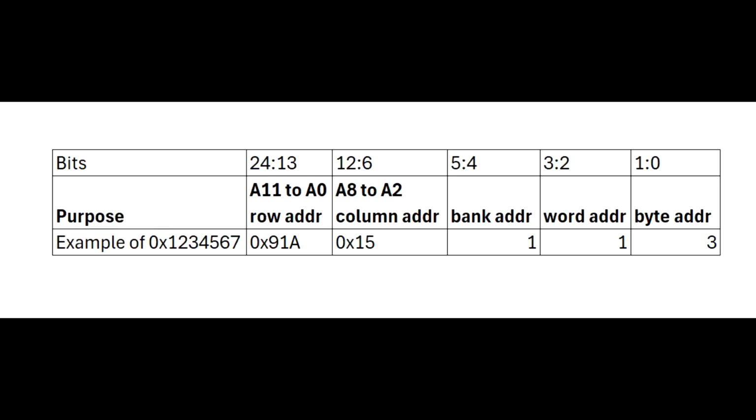Detection of 256 megabit memory is quite simple. We know that it can use the A8 bit as a column bit, and this is not possible on stock memory. So simply we need to be able to set that A8 column bit and see if the memory responds like a 256 megabit memory. By doing some reverse engineering, I found out this is how the address is broken down into the various parts of the system.